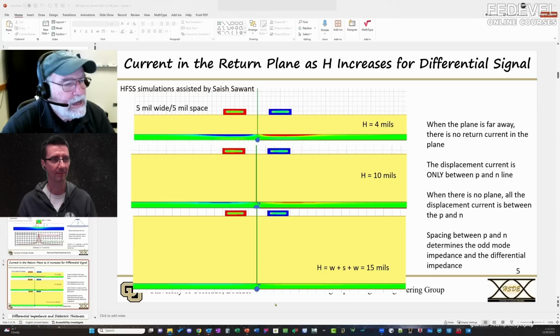And they behave crosstalk-wise now in this environment, then yeah, tightly coupled will decrease the crosstalk dramatically from an aggressor over here. If I have uncoupled or loosely coupled versus tightly coupled for these guys, and I have an aggressor over here, yeah, the crosstalk will be influenced quite a bit by whether they're coupled or not, but that is not the environment that I have in a circuit board. So two different regimes based on where the return current is.